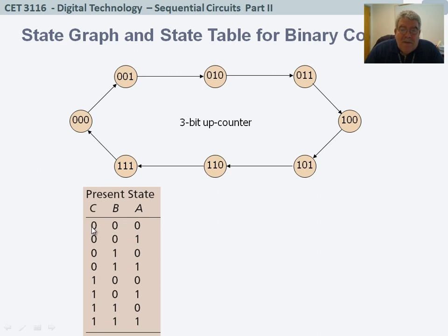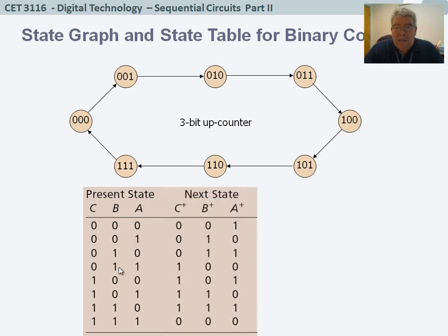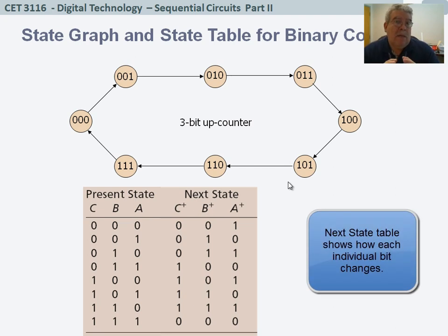In this case, the next state for 0, 0, 0 is basically what is following in the count. This will be 0, 0, 1. So this is our next state table, right? And then what we need to see is that's pretty much the secret. Each one of these next states, or each one of the bits of the states, remember, will be controlled by a flip-flop, right?